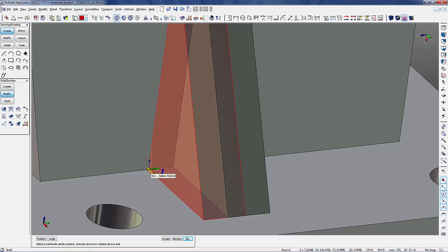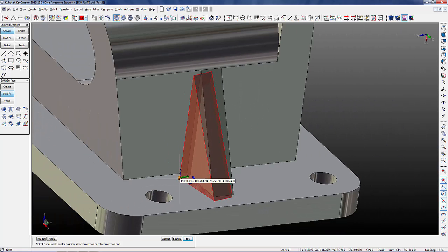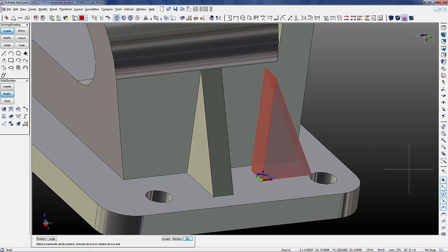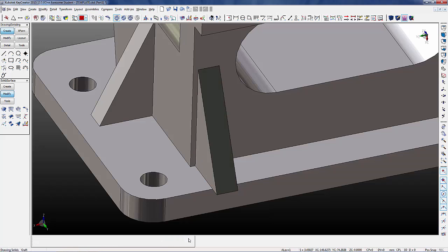Okay, once the feature is copied, we can move it using the axis in this direction or that direction, and also we can rotate it. Easily it recognizes the faces, so let's put this one here in this corner. Let's get the snaps for it. Okay, right in the corner. So we can now drag a little bit there. Like I said, it can be rotated before, so let's type here 90 degrees for it. Enter. So we have a copy here.